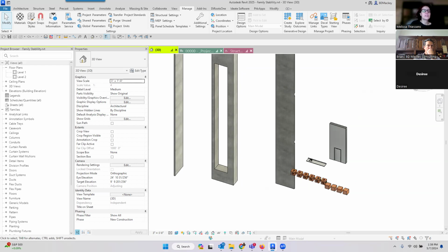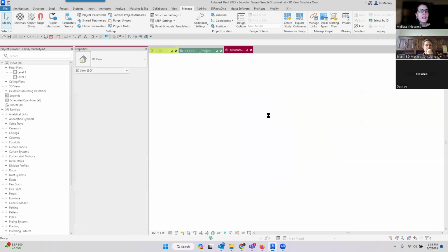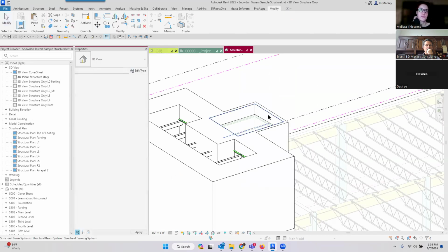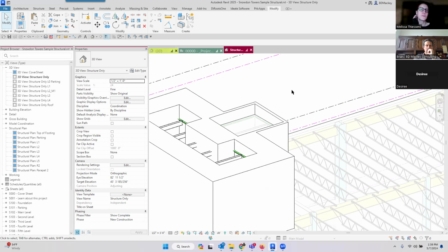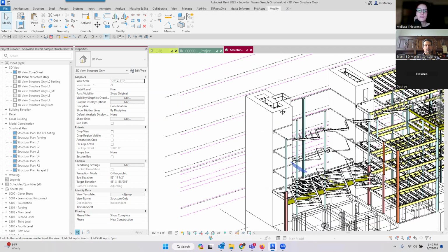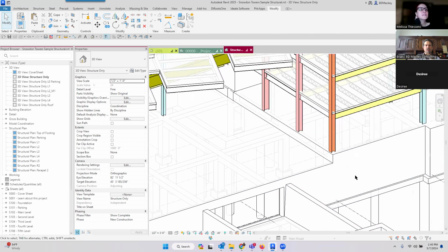Okay, so Trevor's saying in perspective views, I end up with the floor ghosting through the walls when I join the wall and floors. This is in a residential situation where we like to have the wall sheathing and cladding come over the joists of the floors. Is there a way to stop the floor from ghosting through the walls? No, you'll just sometimes see that.